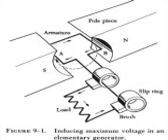The coil is built into some generators as part of the armature, with the midpoint connected to a single slip ring which the neutral contacts by means of a brush. In other generators, the two connections to the commutator are connected, in turn, to two slip rings, and the reactor is located outside the generator. In either case, the load unbalance on either side of the neutral must not be more than 25% of the rated current output of the generator. The 3-wire generator permits simultaneous operation of 120-volt lighting circuits and 240-volt motors from the same generator.